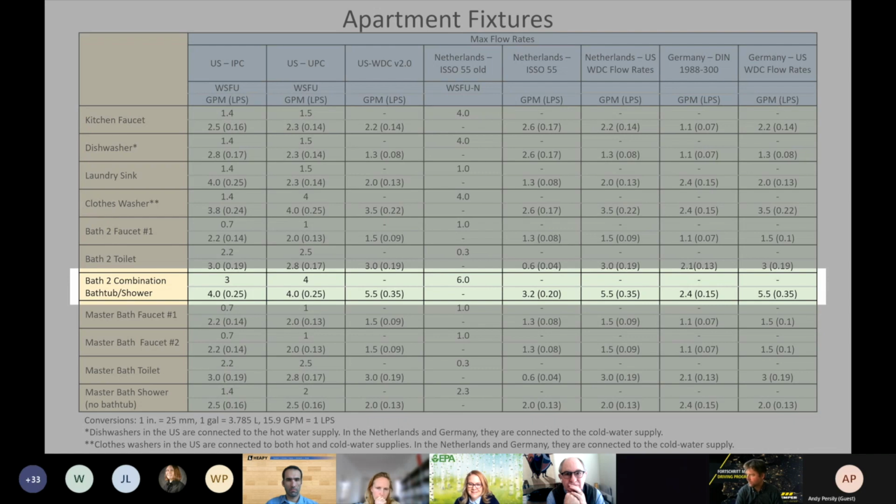Well, I could speak for the water demand calculator. We had a database of residential end use of water surveys, over 1,000 homes. From that database, we were taking a look at the bathtub flows, and 5.5 gallons per minute was, I don't know the exact number, but it was above the median value.